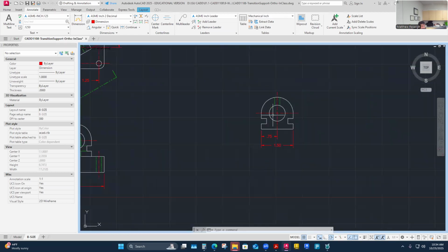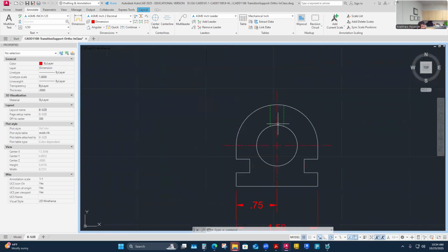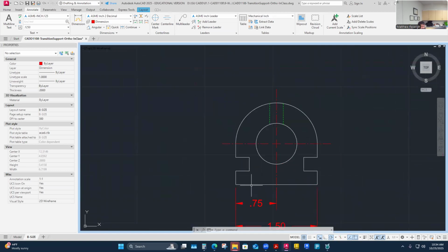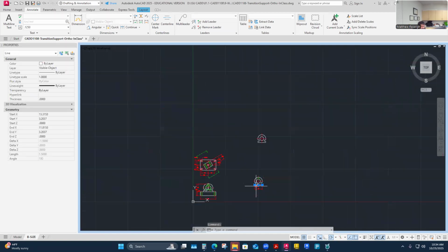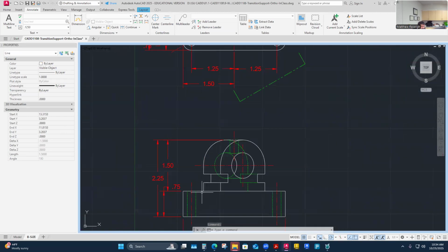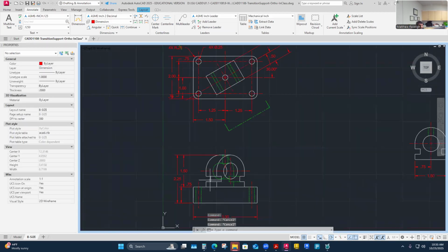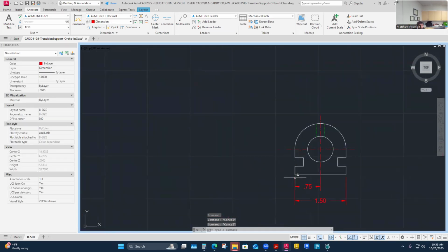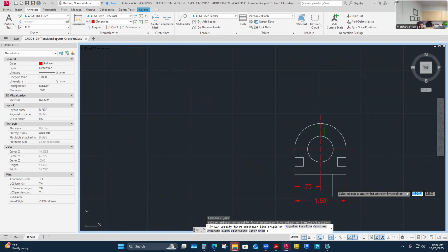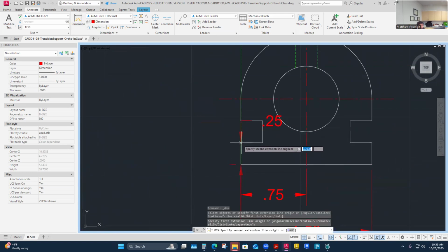So come back over here. And I like the idea of what you said, Nathan: if I do feel like this surface is going to be in common with this surface, if this is really my datum instead of this one, then I can just pull dimensions off of that. So I'm going to say dimension maybe this one to the bottom of slot is 1/4 inch.